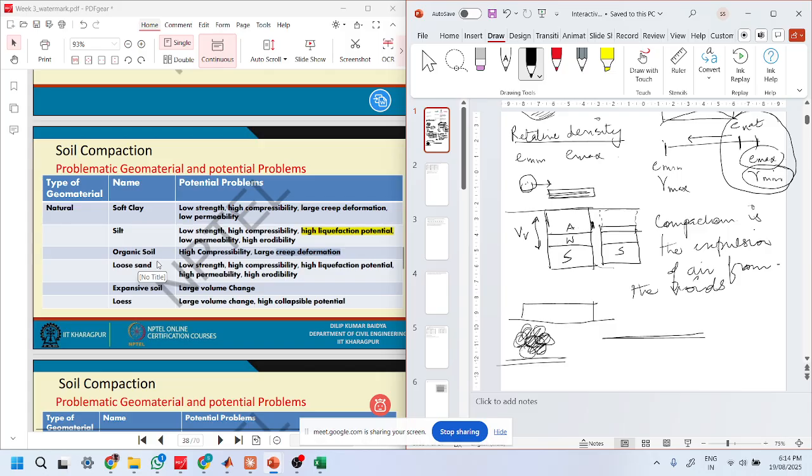Now, organic soils have very high content of degradable matter. So at the start, if you have a high volume of solids, after some time the degradation will take place and the solids will be converted into gases and liquids. Then you will have a lower volume of solids. So as compared to conventional soils, which are very weak in secondary consolidation, organic soils are significantly large.